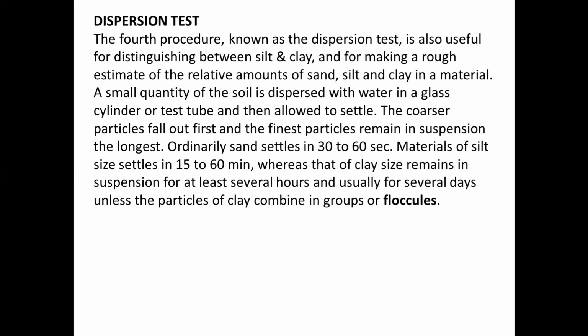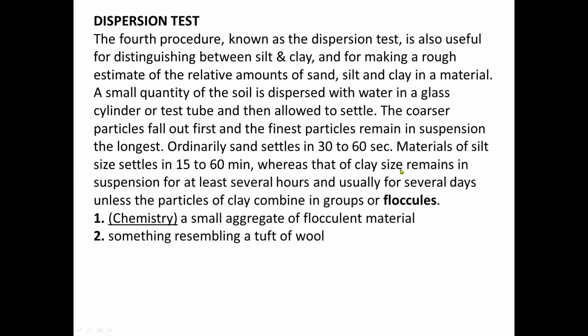Ordinarily, sand settles in 30 to 60 seconds. Materials of silt size settle in 15 to 60 minutes, whereas those of clay size remain in suspension for at least several hours, and usually for several days, unless the particles of clay combine in groups of floccules. Floccule: in chemistry, a small aggregate of flocculent material, something resembling a tuft of wool.